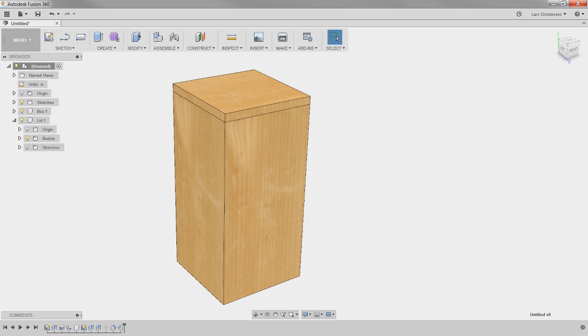Like if you're modeling something 3 inches by 3 inches, 12 decimal points, is 3 inches. Now in CAD, we normally model everything nominal, like I just did, where we didn't put in a clearance for the lid. And the reason we don't do that is because we got to define the tolerances anyways, and we do that normally in a 2D drawing.